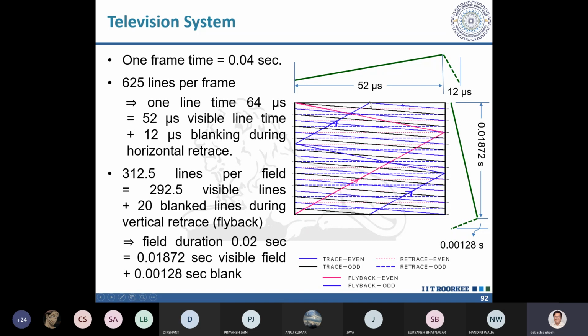And so when I do the next field tracing, you see this tracing will be exactly in between. If it had come here, then it would have overlapped on the previous scan position. But since it has come in the middle, it will now be scanning exactly in between the 2 earlier scanned lines. So these black lines you can see were the scan lines in the first field, and this blue line in between is the scan line in the even field, the second field.